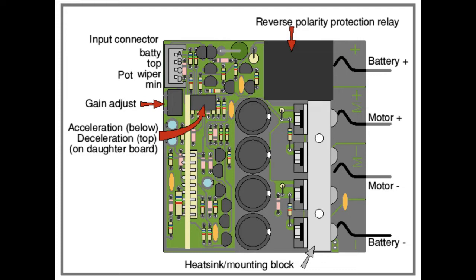Initially I planned to design my own amplifiers. I've had some experience in designing such devices. Then, on eBay I noticed 3 PWM amplifiers type Uni 8, made by the company 4QD. They're not a current model, but I've used this amplifier professionally and had a full circuit diagram. So the fact that they were listed as faulty was not a problem, and they went for a song. It turned out that someone had interfered with the current limits, but it took only a few minutes to correct.